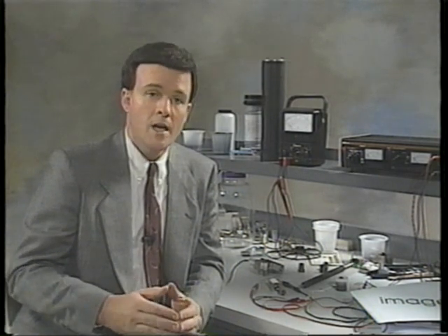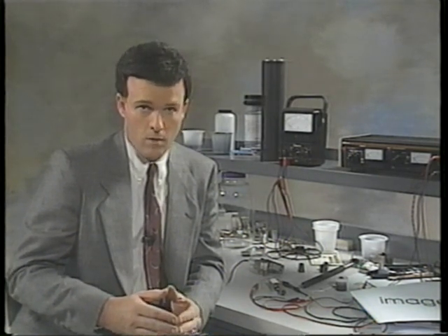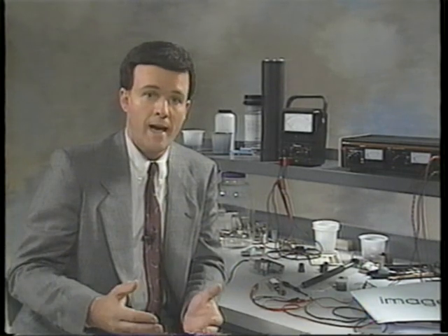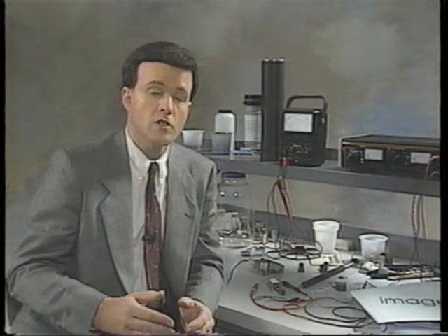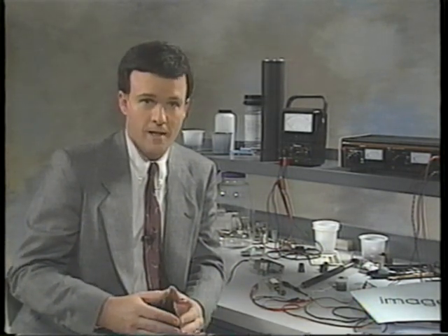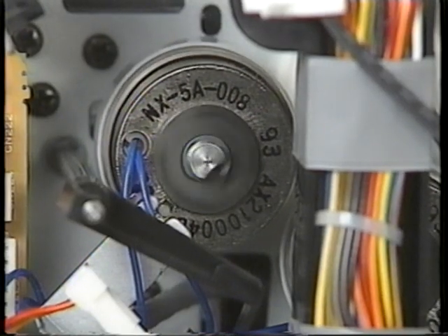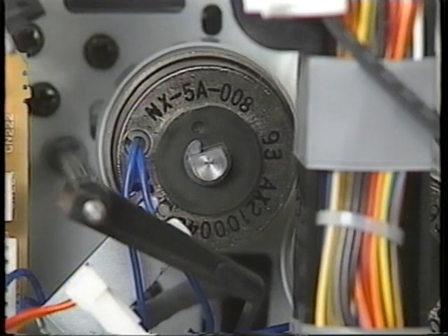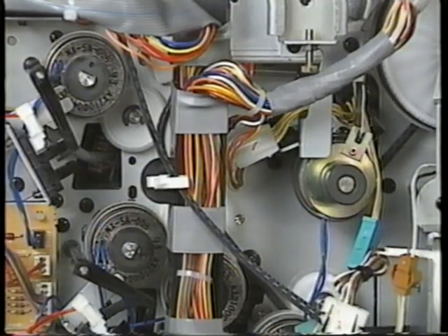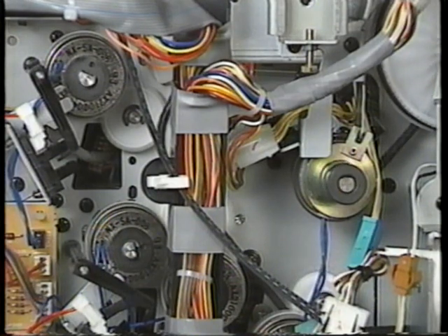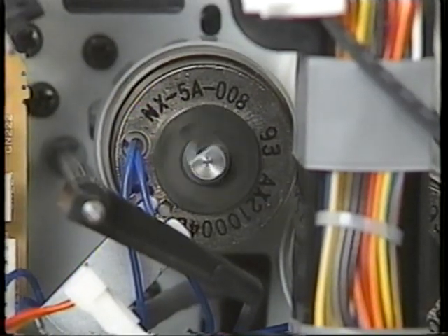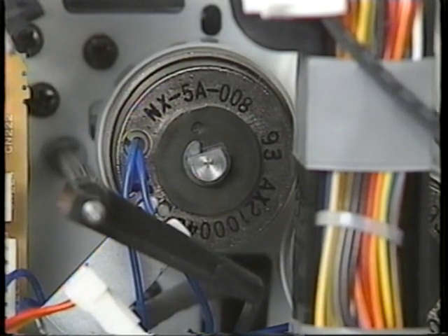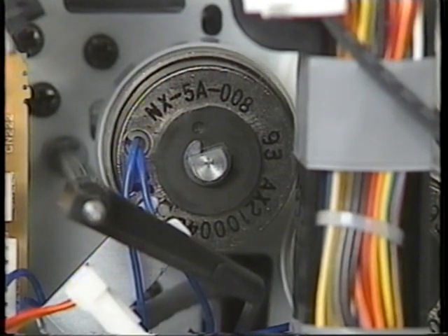In a paper feed system, clutches link drive gears to rollers. Motor drive can be passed to a roller or taken away, so the rollers start or stop turning as necessary. The pieces making up a clutch are designed so that one side can be turning while the other side is stationary. When it's time to engage a roller, an external mechanism causes both sides of the clutch to lock together and transmit motor drive as if it were a solid piece.